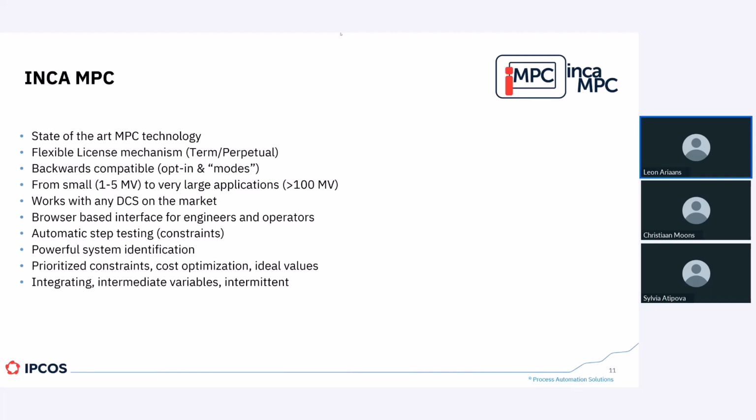INCA MPC supports that. Actually has two flavors, one where you try to be balanced all the time, and one where you say, in terms of this vessel example that I gave, as long as you don't overflow or underflow the vessel, everything's fine. And this is not limited to vessels. Pressures in a reactor are also often integrating.